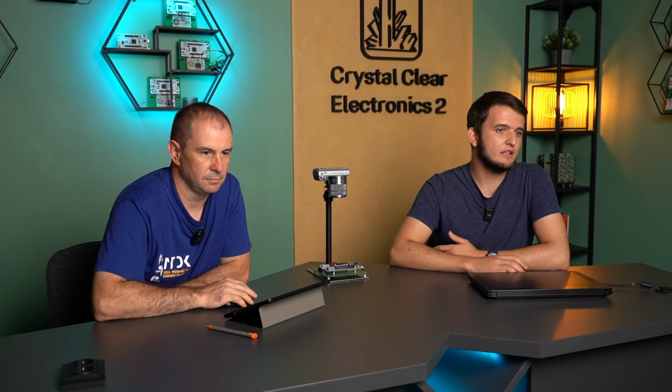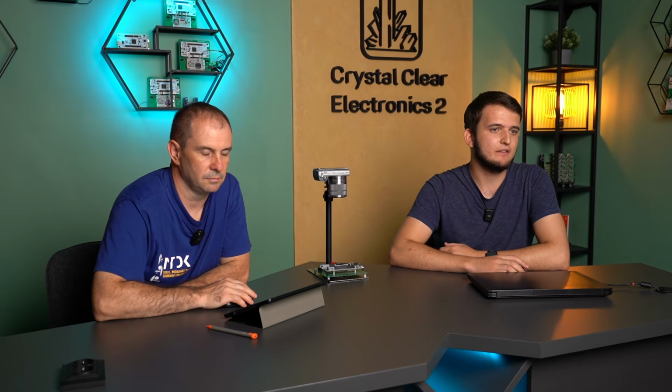It monitors the input voltage level and sets its output depending on it. When the voltage at the input reaches a certain level, the output switches to a high logic value. When the voltage at the input drops below a certain level, the output switches to a low logic value. Due to hysteresis, the 2 switching thresholds do not coincide.